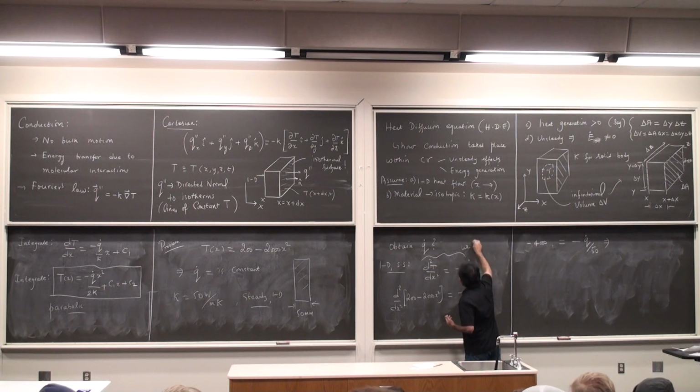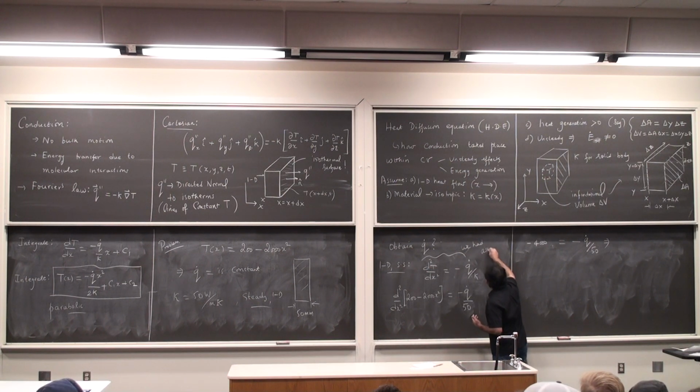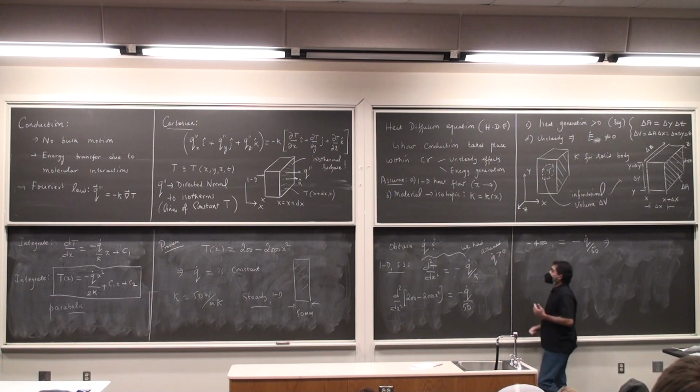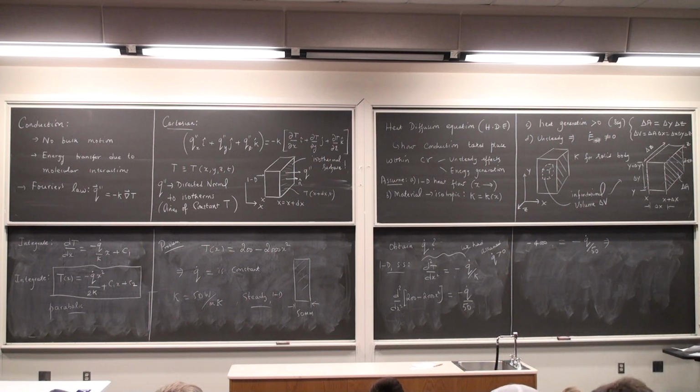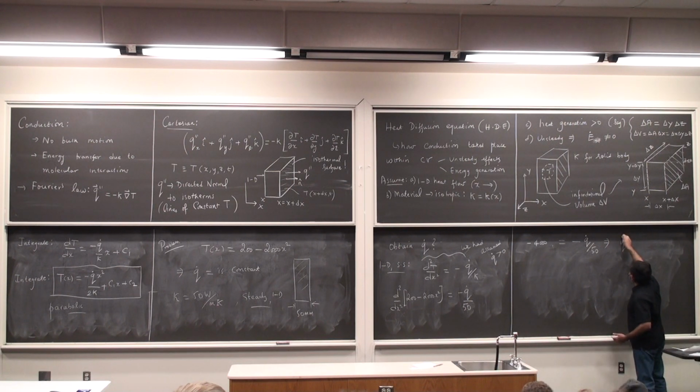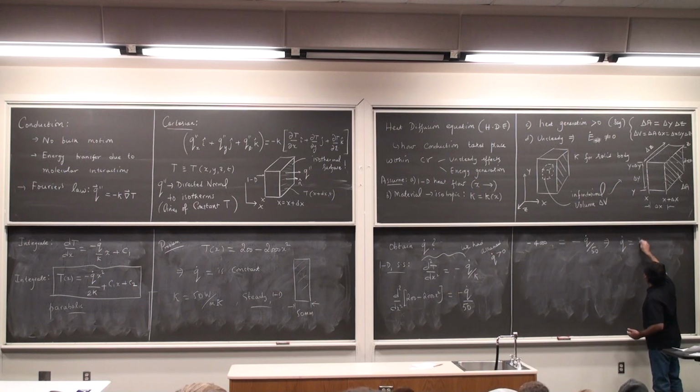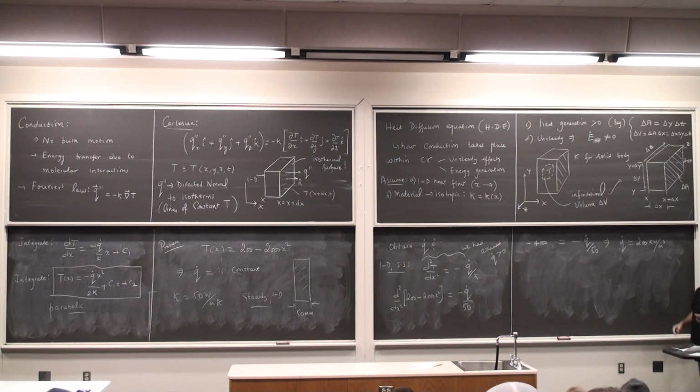We had assumed Q dot greater than 0. We are validated by the answer that we obtained. So solve for Q dot. This is 200 kilowatts per meter cube. Volumetric energy generation is energy generated per unit volume, or rate of energy generated per unit volume, so watts per meter cube. So this is positive.